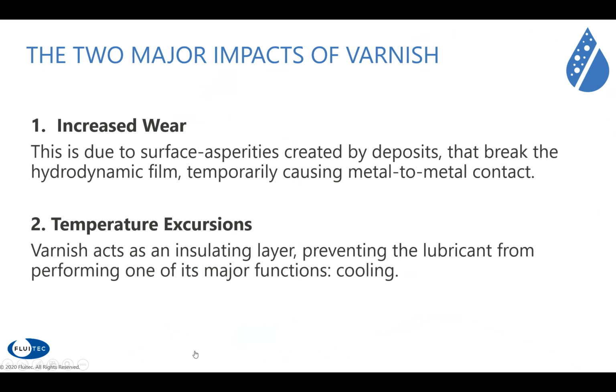So the first part is really the amount of wear that is created in the bearing surfaces. If you are creating deposits by the varnish, knowing that varnish is very polar, the polarity of the varnish makes it very easily attracted to white metal surfaces. And I would say that's even accelerated by increasing load factors on your bearings. Now, due to disruption of this hydrodynamic film, you are seeing an inconsistent oil wedge, which is then also creating what we say here, a metal-to-metal contact.